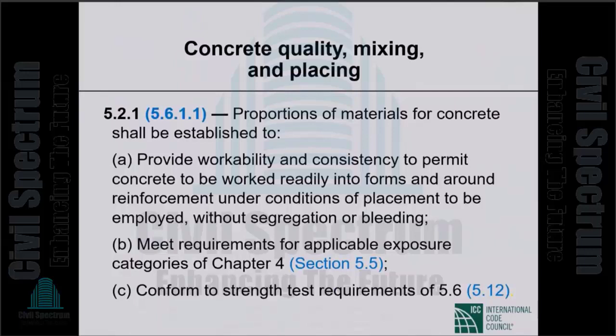So proportions of materials for concrete shall be established to provide workability and consistency to permit concrete to be worked readily into forms and around reinforcement under conditions of placement to be employed without segregation and bleeding. Meet requirements for applicable exposure categories of chapter 4. So those are the durability requirements that have to be met. So you have to comply with strength requirement. You have to comply with durability requirement, but you have to think of workability.